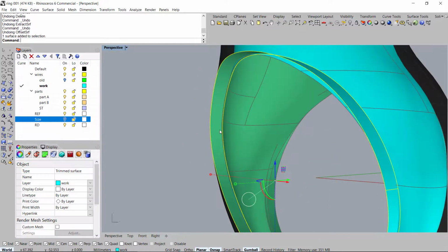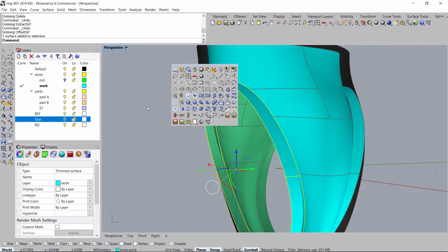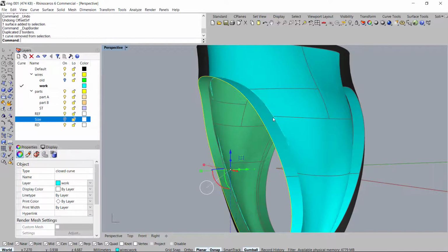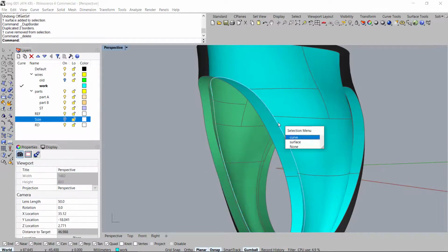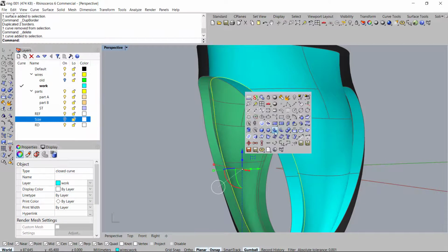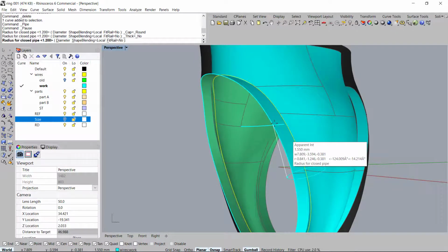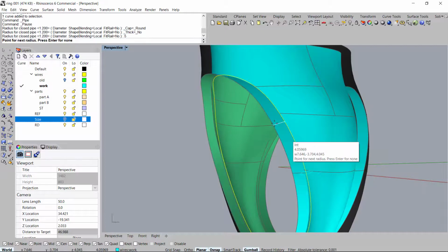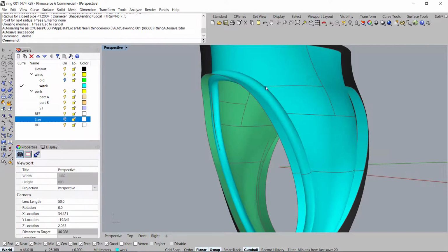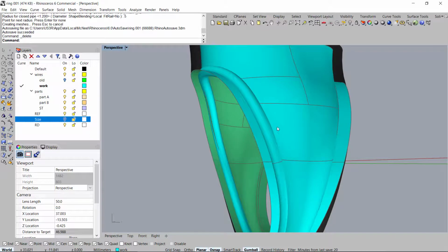What I usually do is I select the surface and just duplicate the border, select just the inner curve like there, and let's just go ahead and pipe it. Okay, you don't have to do the offset. If the offset and the split works for you, cool. If not, then this is another way to troubleshoot. So just simply pipe it with a pretty good number, like start with 0.5, and hopefully it will intersect to give you the separation of both surfaces.